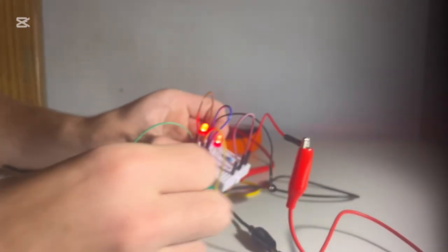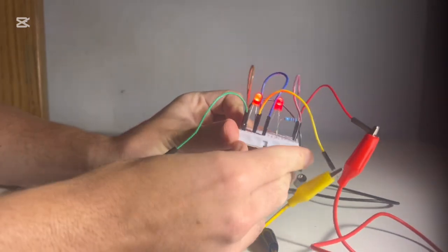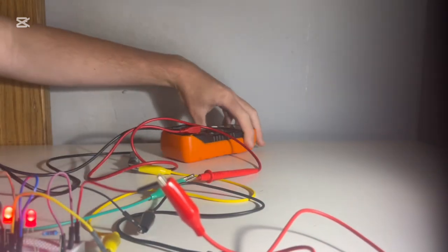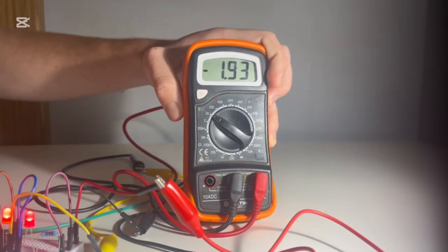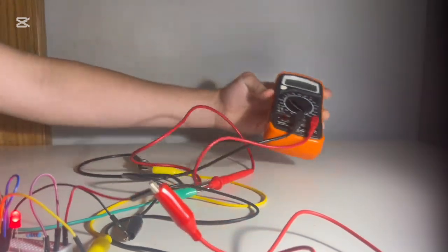Applying the power supply, you should once again see both LEDs light up. The voltmeter now shows a reading across the second LED as being 1.9 volts. Thus the total voltage in the circuit is 6 volts, close to what we measured.